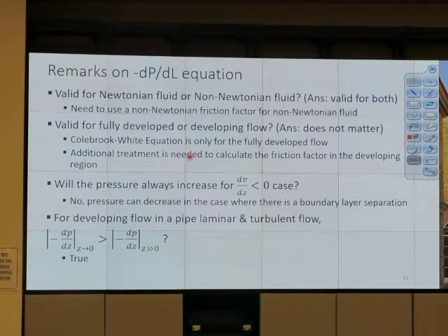Sometimes what I experience is that even though we believe an emulsion is non-Newtonian, when I actually do the test, it's just a Newtonian fluid. Like the one that Raymond did in the lab has a high viscosity oil and some air inside. There's not much air inside, so it's kind of a Newtonian fluid. To know for sure, we have to do the test with a rheometer.